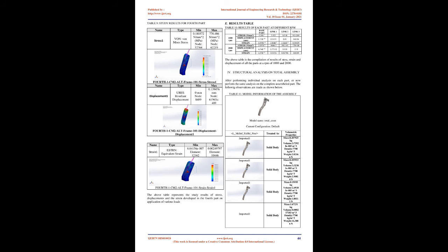FEM is a numerical technique for analyzing engineering designs. FEM is accepted because of its standard analysis method, thanks to its generality and suitability for computer implementation. FEM divides the model into many small pieces of simple shapes called elements, effectively replacing a complex problem by many simple problems that need to be solved simultaneously. Elements share common points called nodes.